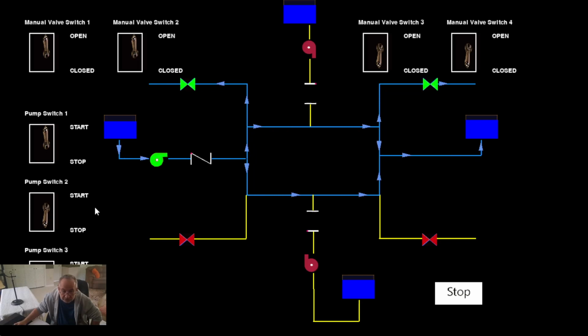Now if we start the 2nd pump, so this is pump number 2, the check valve closes, the pump starts up, and now instead of the flow going only to the tank, this particular pump is now splitting and then feeding the flow to this valve here. And as you can see from the arrows, it shows the changing direction, and that is really significant, because dynamically you can see how the flow moves between